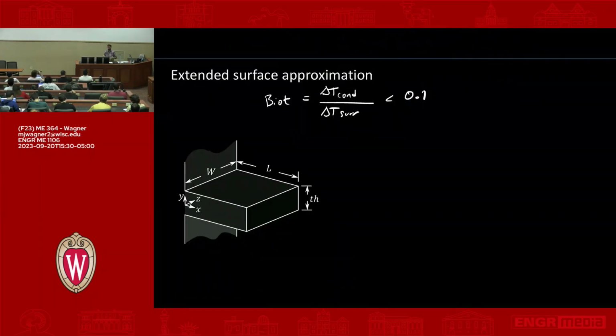So let's give you a more concrete definition of the Biot number so you can actually compute it, and then go through an example. So we know conceptually it's the ratio of two temperature differences. What that actually means is we can look at, we'll abbreviate it BI, so Biot number is BI. Let's look at the ratio of resistances, because remember, resistance is going to be proportional to the delta T. So let's look at the resistance in Y divided by the resistance to the surroundings.